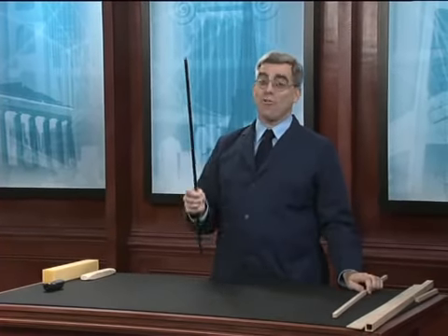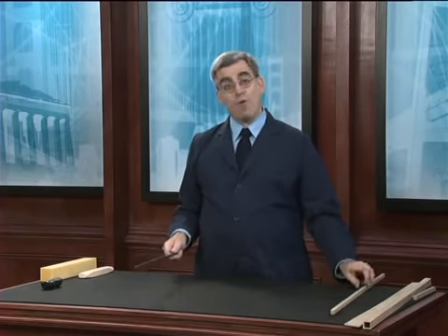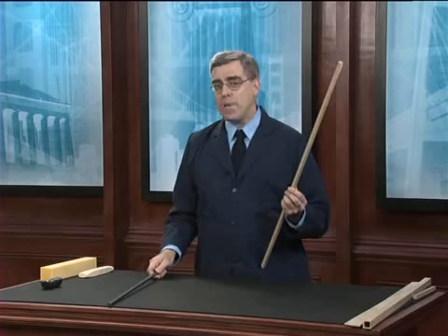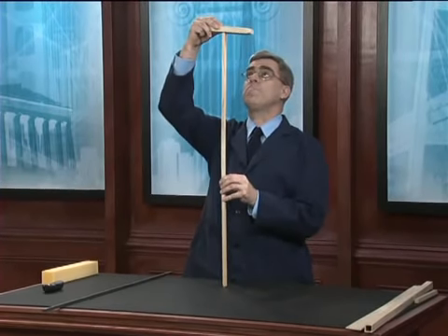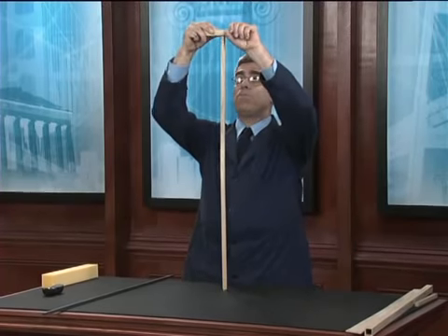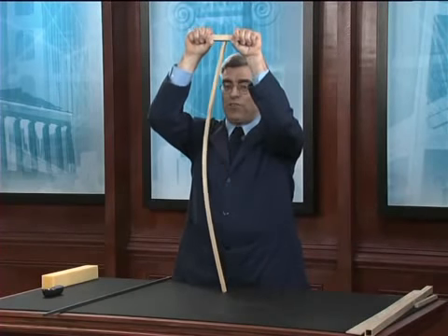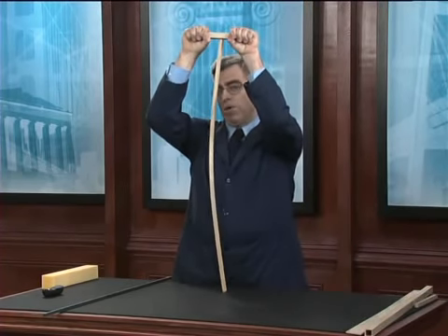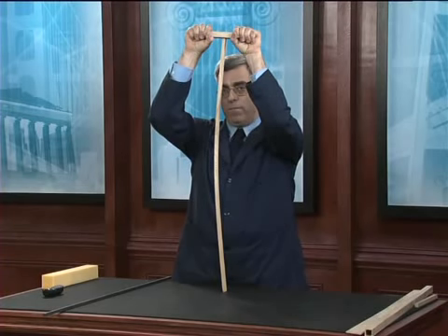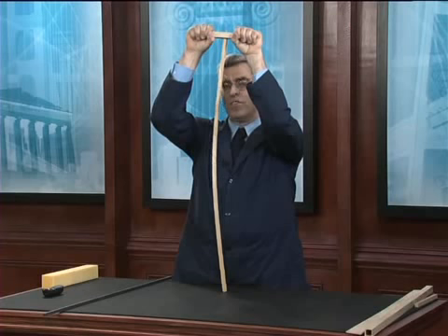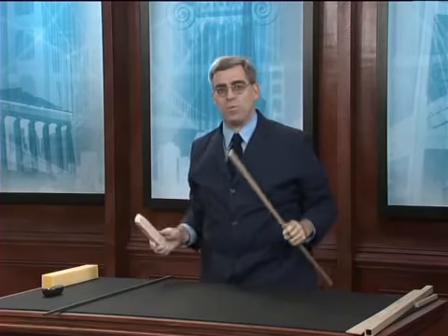The critical buckling load for the steel column turns out to be 364 pounds. For the wooden one, it's only 20 pounds. And indeed, if I apply a load to the top of this column, it does indeed buckle relatively easily. And you can't tell, but I'm here to tell you, based on my perfectly calibrated arm muscles, I can tell you that this is almost exactly 20 pounds, causing the column to buckle.